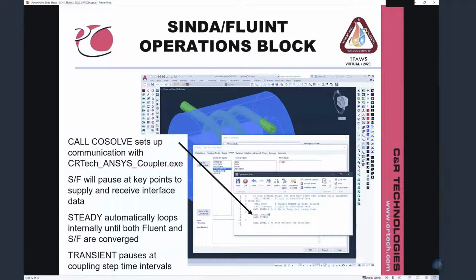Now there's mapping. There's all kinds of mapping controls for tolerances and things, just like we have in Thermal Desktop. All the things you can do when trying to get temperatures to the stress model, and they don't quite line up. But obviously, the closer you can have the geometry, the better off you'll be to begin with. And we'll show you some debug tools to show you that.